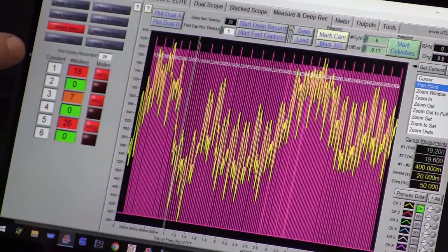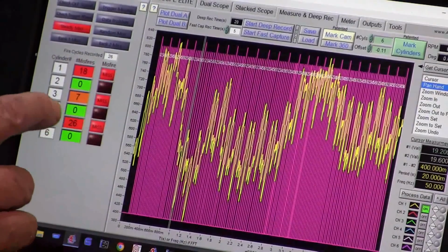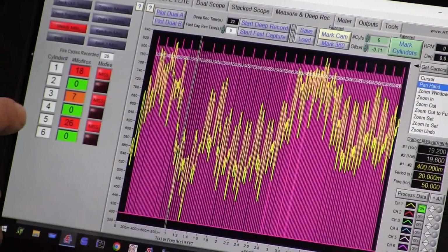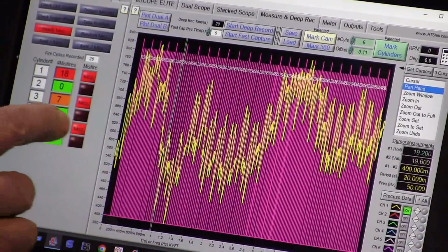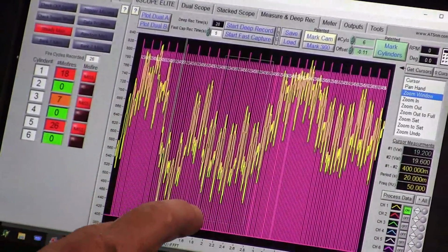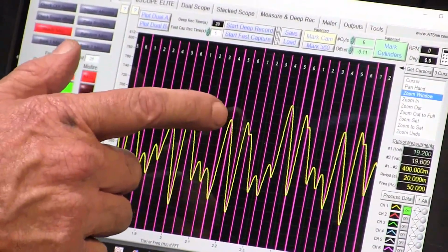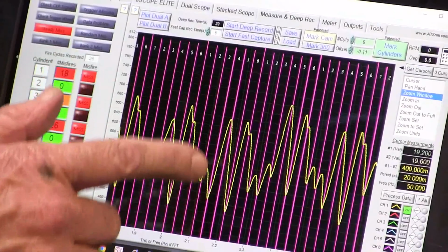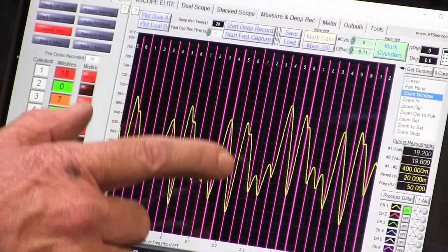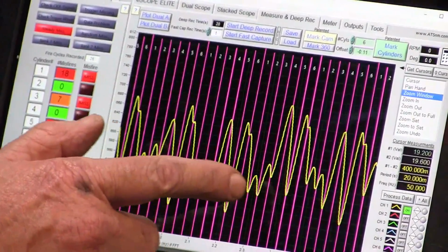Okay, so we have 1, 3, and 5 misfiring, and 5 is far worse, 26 to 3, 7 to 1 is 18. 1 and 5 are the main misfires, but 5 has a really bad misfire. Now the way we're doing this is we're looking at the crank velocity. Do you see how right here the crank velocity sped way up on 4? Right after 3 it sped up, because 3 drops, and then 4, and then look at 5 drops way down. And do you see how right here, that's 5, it drops way down?